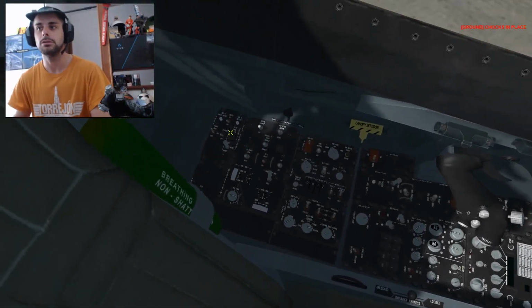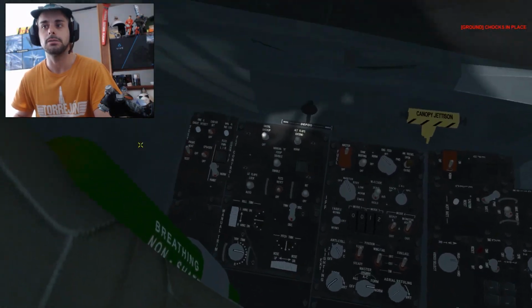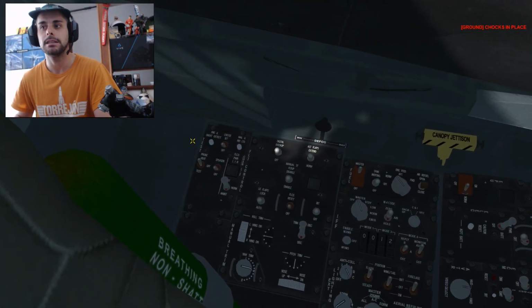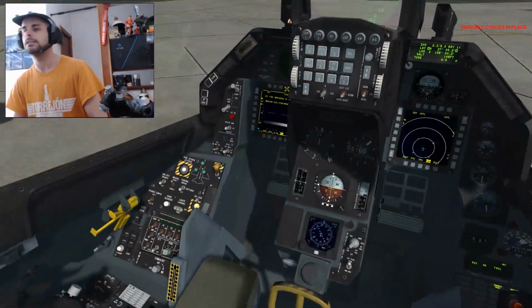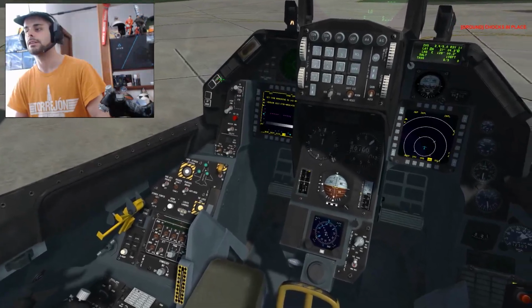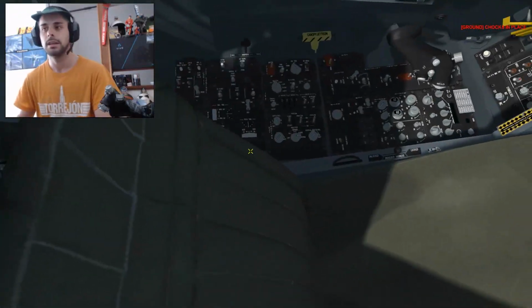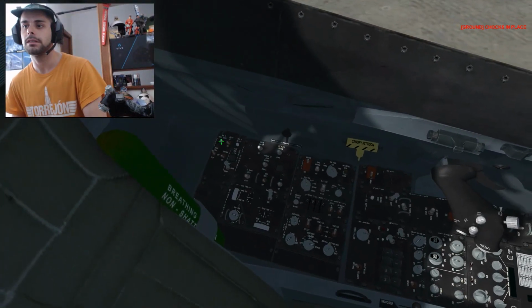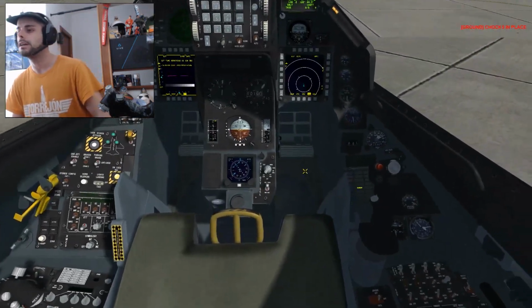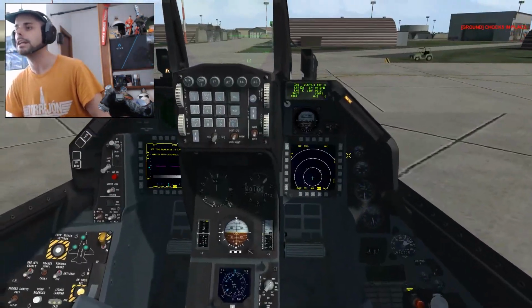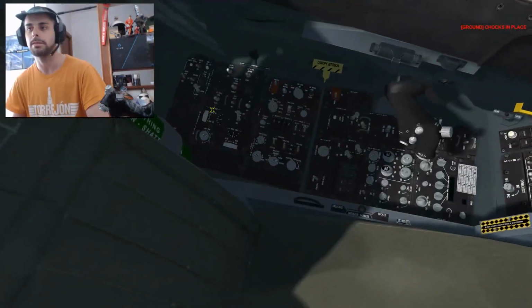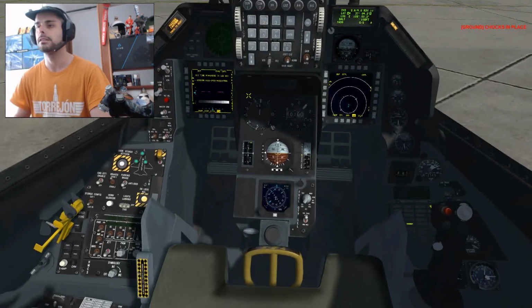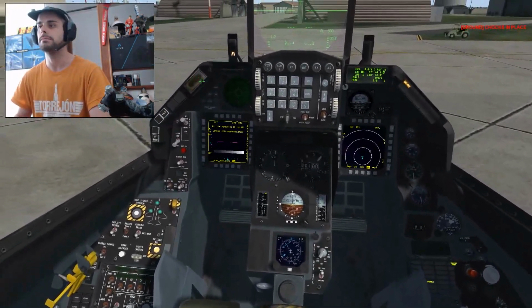More tests you can do are this one, fire and overheat detect. Remember, check your lights. Okay, use the acknowledge button. Perfect. And now here I am pushing it, and you can see the overheat and also engine fire lights turned on with the master caution. Okay, click. Reset master caution.